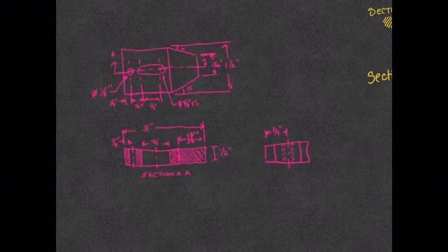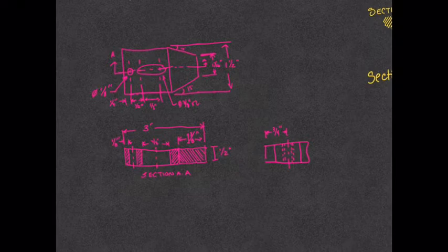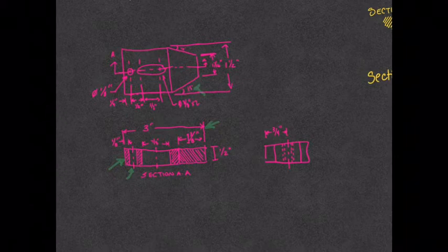So this is the drawing with the same section views. As you notice, I replaced the front view with a section view. And I included all the section lines. The center lines are still present, dimension lines are still present, and I tried to include every possible dimension that I possibly would need for anyone to recreate this, such as the angles, the placement of each hole, not only from left to right, but from top to bottom, or the height or depth of it.